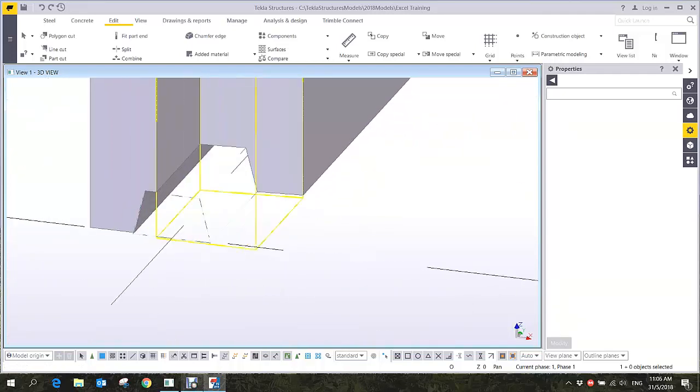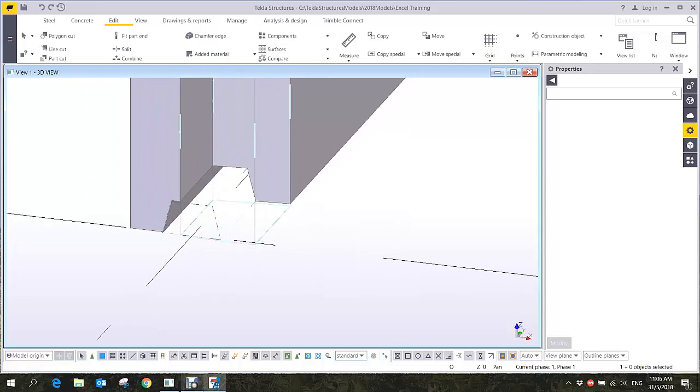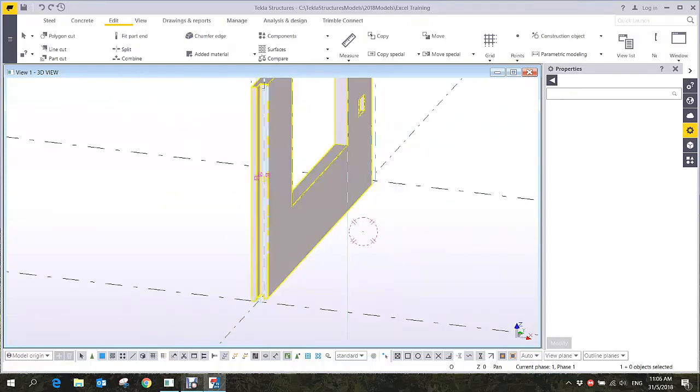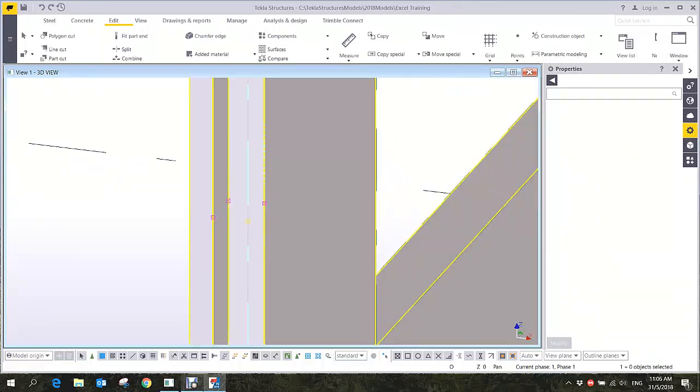Here in Tekla Structures, if I select this cut, this handle, and then let's say bind that one to boundary plane, bind. So this handle will stay to the boundary plane that it is bound. But you don't have to do this all the time.